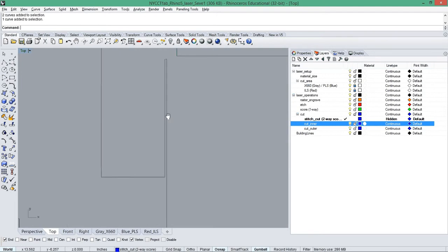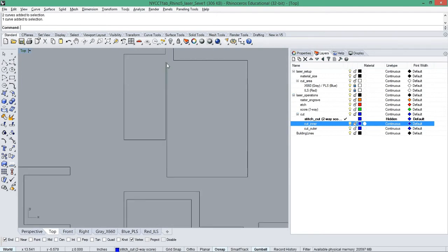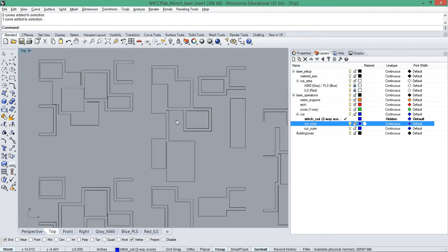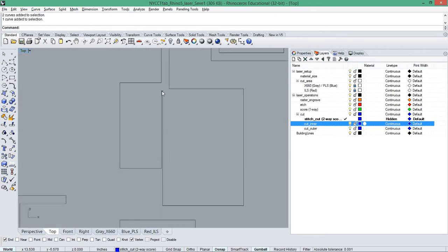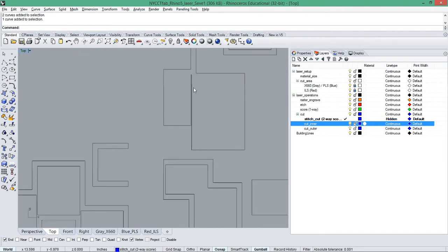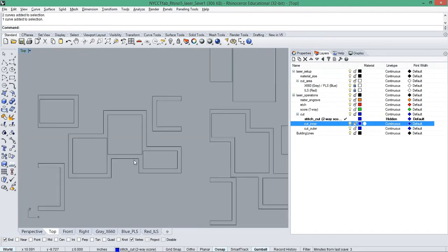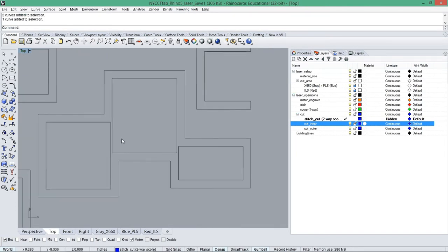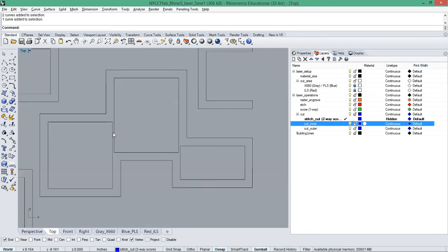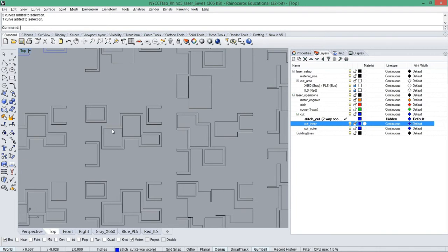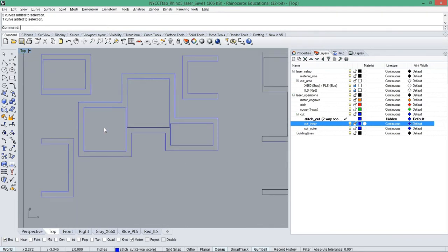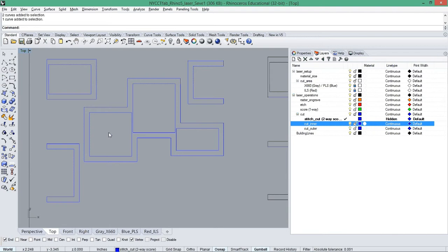So all these little details, you might want to leave some of them, but think of the laser going almost through the same line, so we'll just create a bigger gap in that sense. And when it does that, it's just not going to have any material at the end. So you decide how you want to do it, but I recommend that you do the cleaning that I'm going to tell you. Otherwise, you're risking that some parts may fall down or be a little bit ineffective.